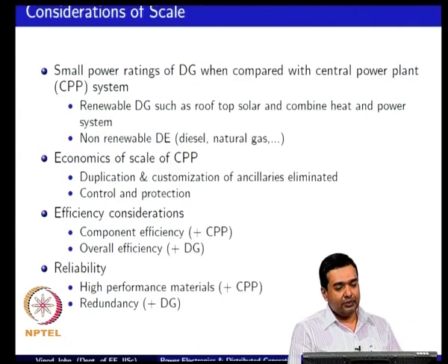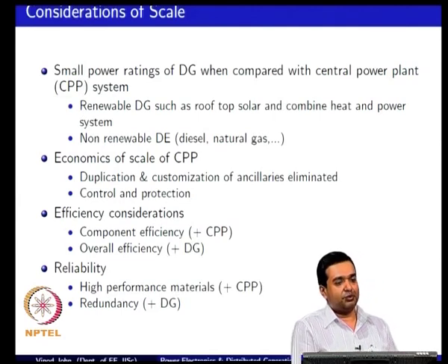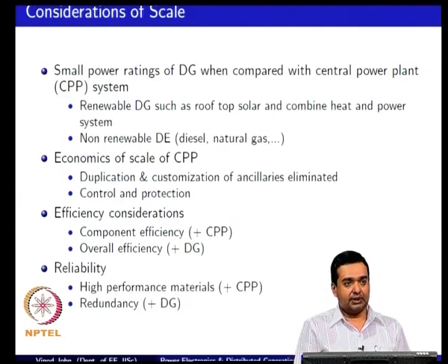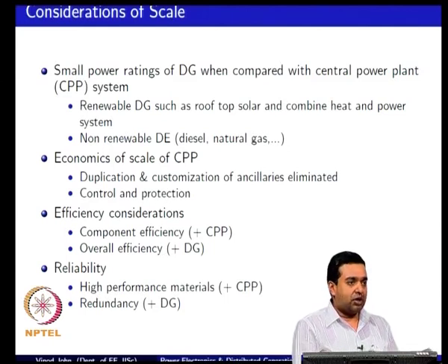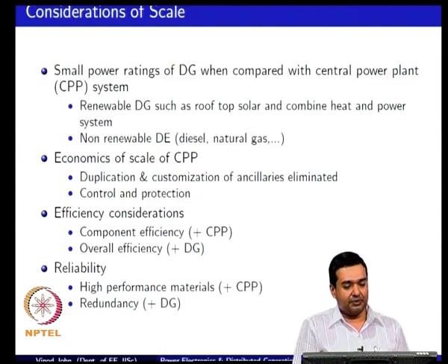If you look at efficiency from the component efficiency point of view, from the machine efficiency point of view, you have advantages for the centralized method of generation, whereas for the overall efficiency, especially if you are making use of waste heat, you have an advantage for the distributed type of solution.